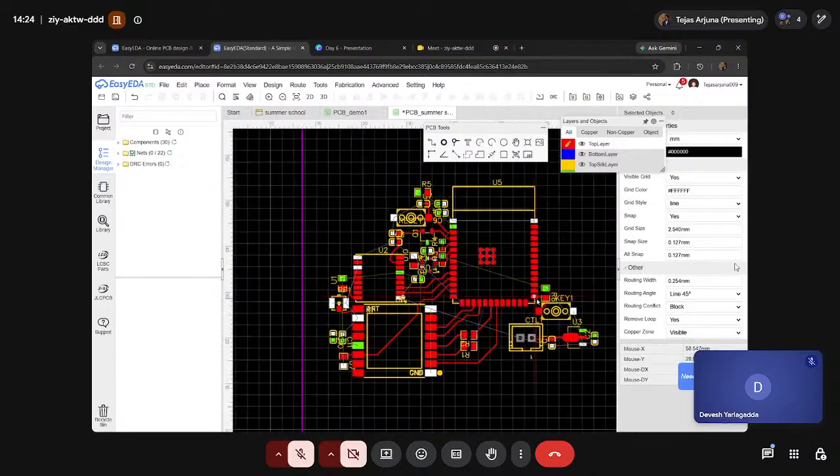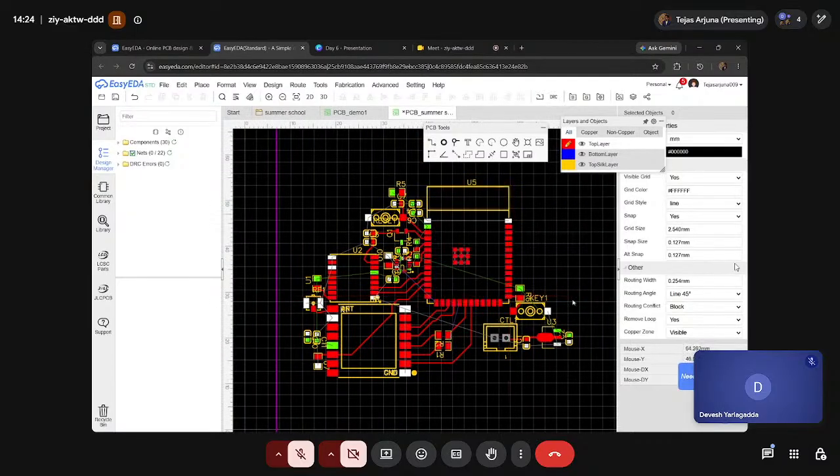We completed the signal part, so we have left spaces for ground and VCC. Now I'm going to tell you another concept. EMI can be transmitted as radiated EMI or conducted EMI. There's a minimal chance of conducted EMI in this case, where two signals have a common point, for example power rails, VDD or GND, and noise from one is captured by the other and goes on. The radiated part is what we'll need to focus on more.